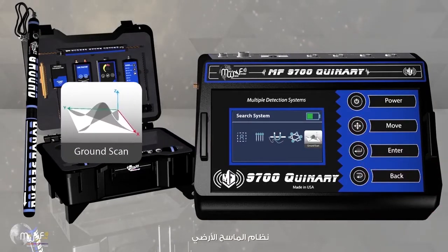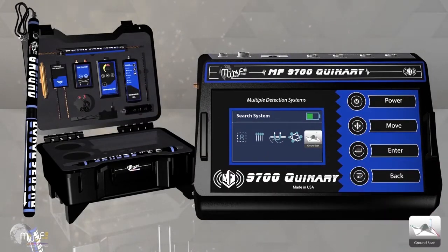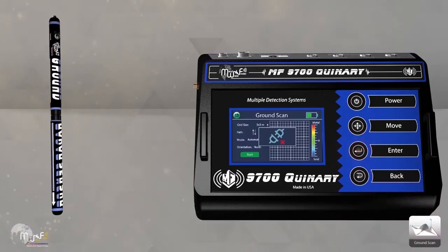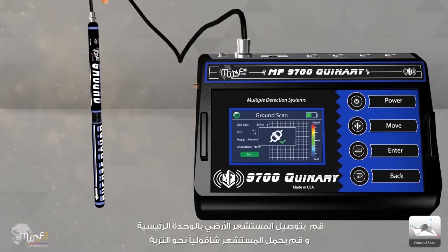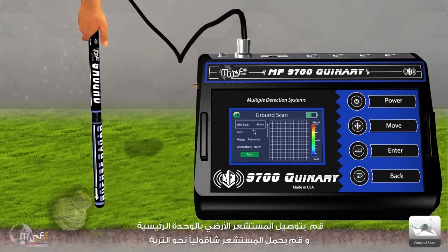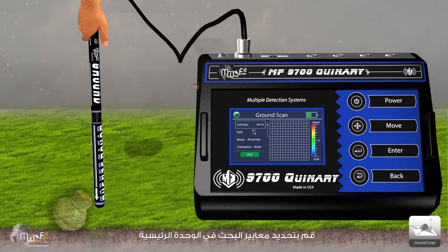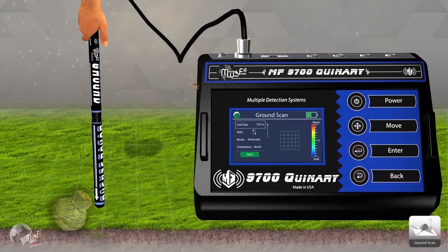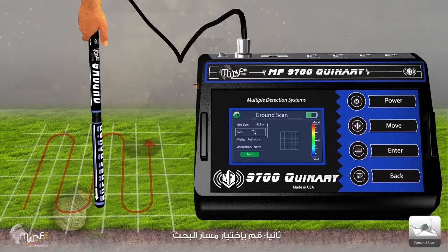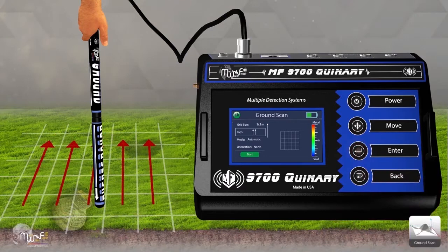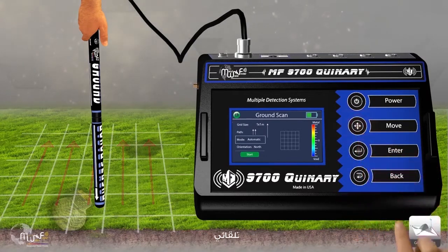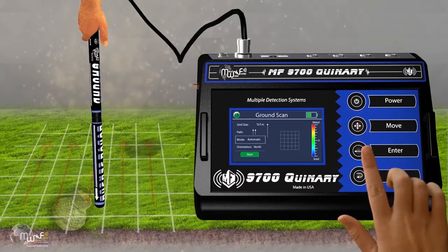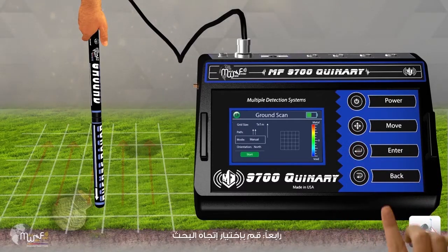Ground Scan Search System. Connect the ground sensor to the main unit and hold the sensor vertically towards the soil. Select the search criteria in the main unit. First, select the size of the search. Second, choose the path of search direction, zigzag or straight. Third, choose the search mode, automatic or manual. Fourth, select the search direction.